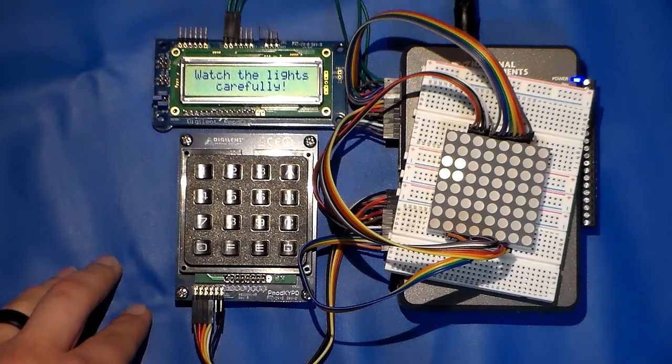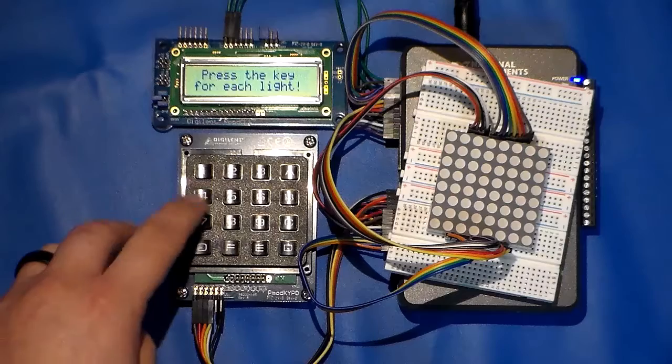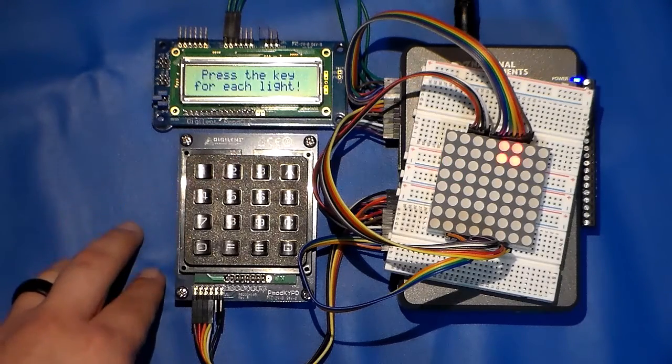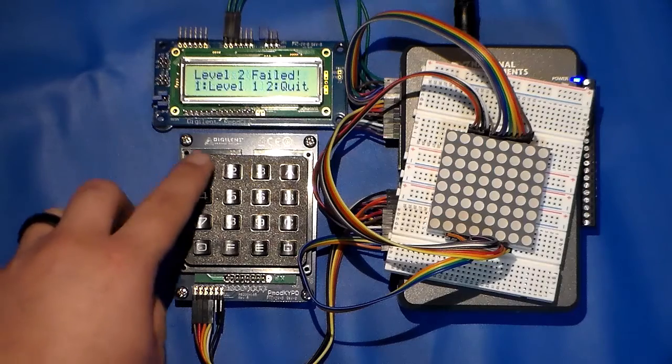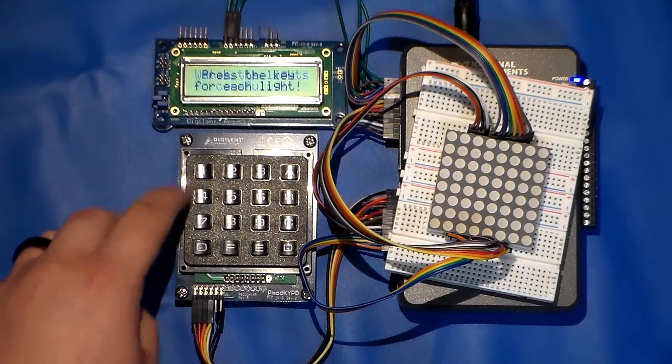Level 1 consists of 2 characters and displays the appropriate group of LEDs for about 2.5 seconds with a half-second pause in between. Each subsequent level adds 1 character and reduces the display and pause times by 10%. The PMOD CLS display provides options, instructions, and results to the player, and the game is continued until the player elects to quit. Here's how it works.